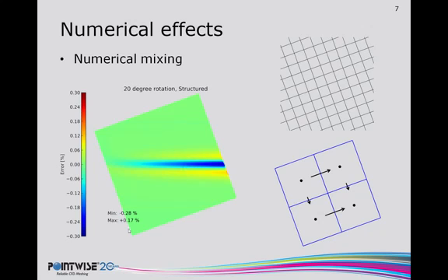Now, again, the error here is small. I'm not saying that you cannot sustain and cannot handle non-flow aligned cells. I'm just simply pointing out that these cells will introduce some error into your solution, and it's up to you to mitigate those and decide whether or not that's going to be a large enough effect on your solution.